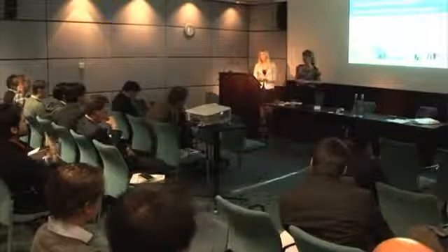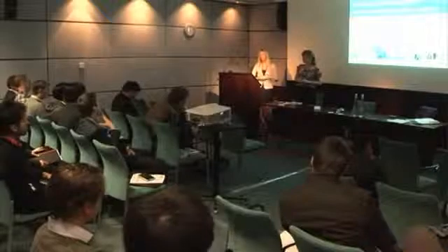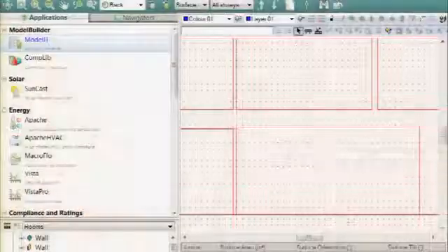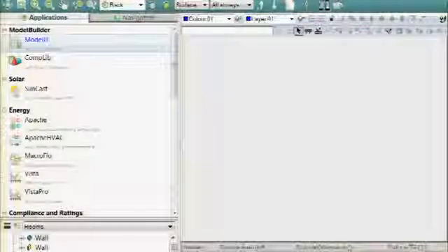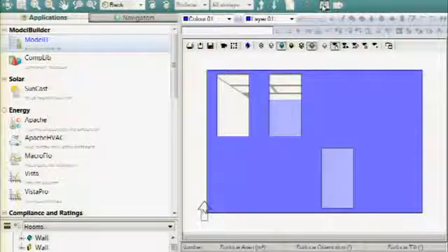Yeah, one thing with Revit to remember is also where your levels are set. So if you have an actual elevation which relates to this, if you say I have an elevation of 250 feet above sea level, and that's where my first floor is set, the first thing you want to do when you get into the VE is just open the viewer of the model. Half the time you're going to see that the model is actually floating 250 feet above the ground plane. So that's one thing to look at, and make sure that it is actually set on the actual ground.